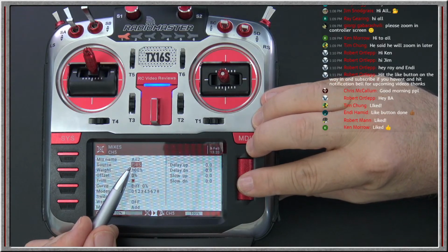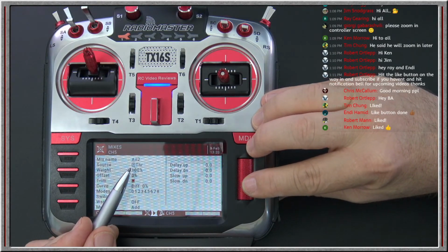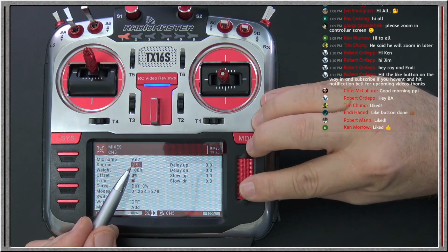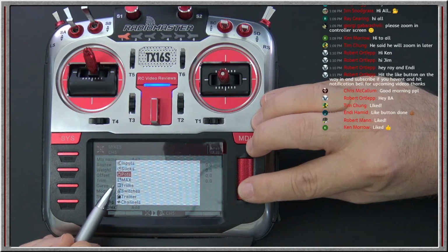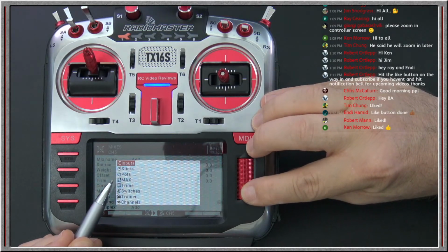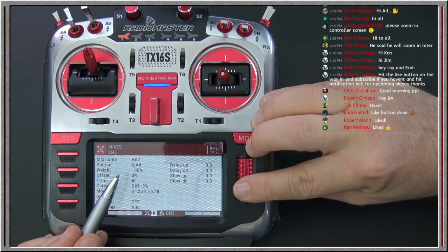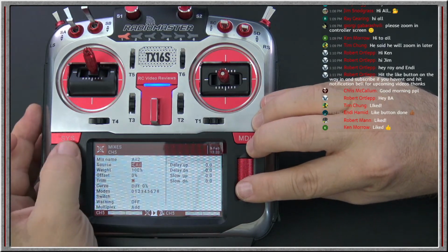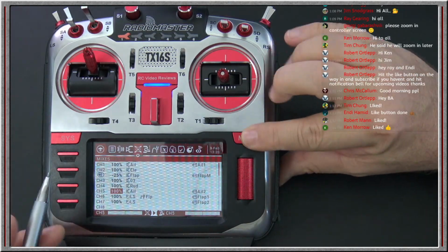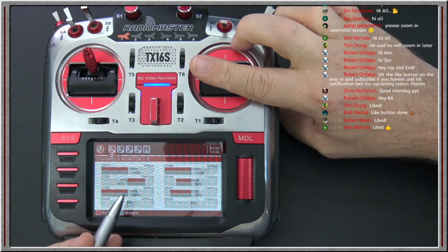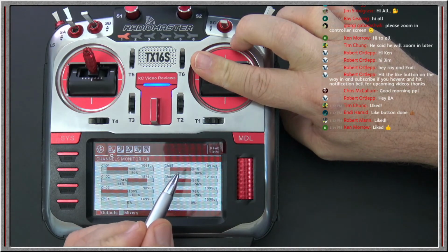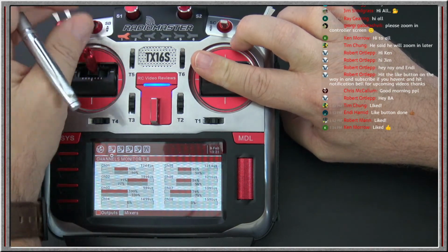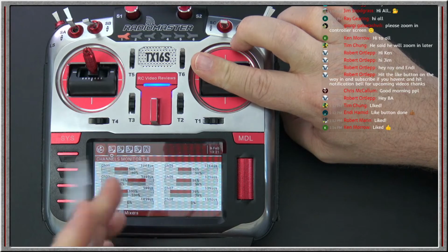So if I scroll back over and make this an aileron source, we should see, let me find it. See if I long click it, I should be able to get inputs. Inputs. There it is, aileron. Okay. So if you're an eagle-eyed person, you might have noticed, hey, when I was flipping the rate switch, channel 5 didn't obey. It didn't go along with the rates. It's because I had it on an aileron stick in the mixer.